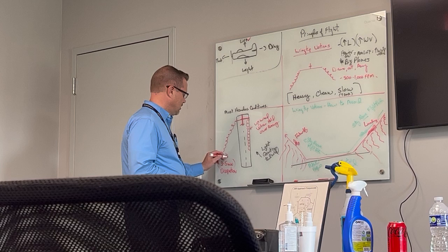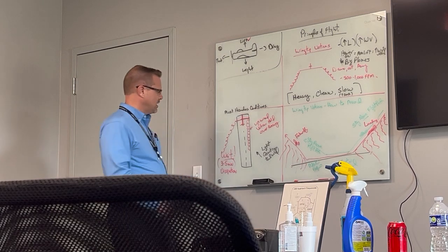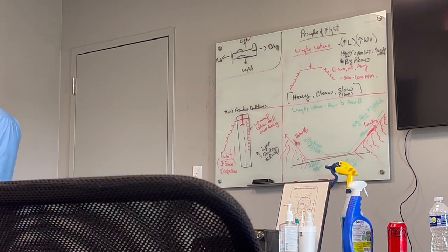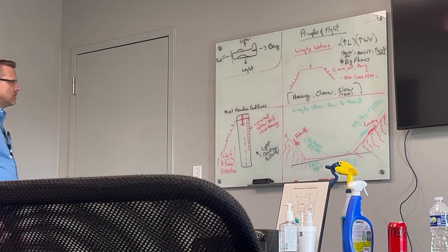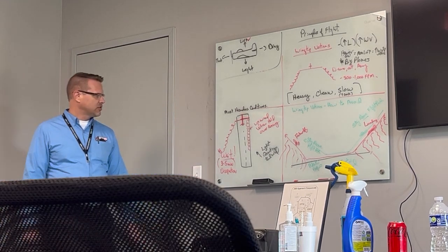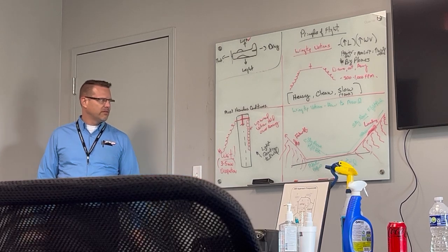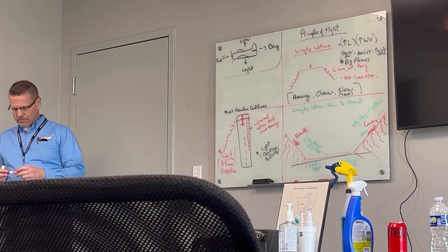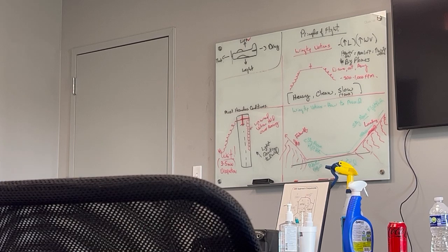So in this case, we can't do anything but wait. We can't take off, the wingtip vortices are there, we can't destroy them. We just basically have to wait it out. So basically start a timer, and after the aircraft takes off, we wait for a couple minutes to allow those wingtip vortices to dissipate over the runway before we go ahead and take the runway and depart. Okay.